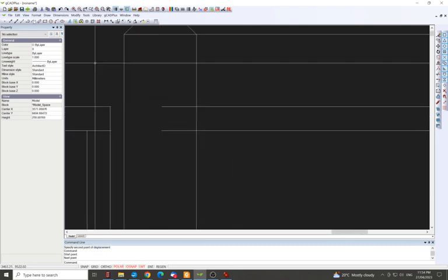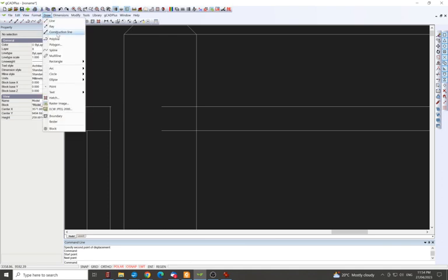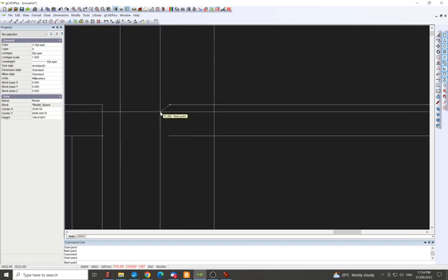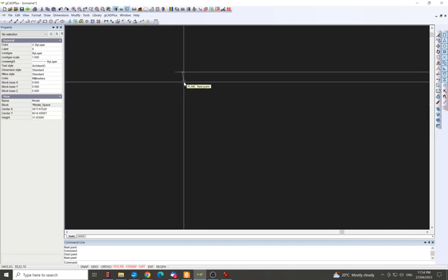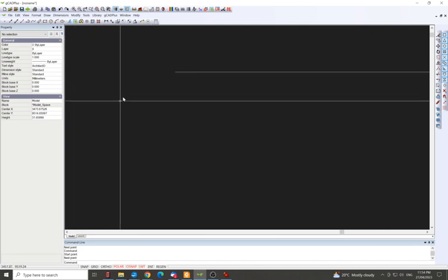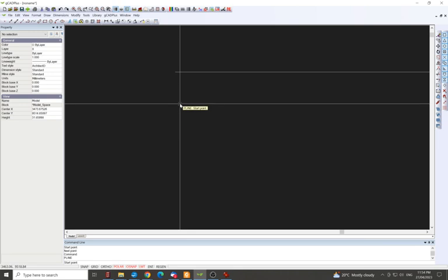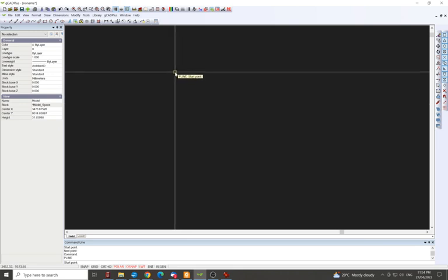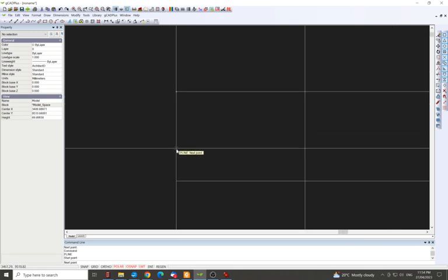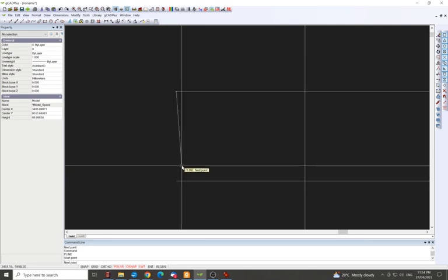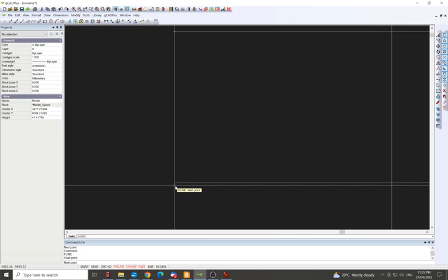From back here it looked like it was on there. So I go polyline and I think I'm close, but I've gone off a little bit, and when you look close, you're off it. If you want to go back to polyline, you don't have to go draw polyline, just press enter, and I'm back to the polyline start point. So don't forget to use your enter key. I think the 2 most important things are your distance, and using the enter key to repeat the instruction. It really makes a big difference in your drafting speed.